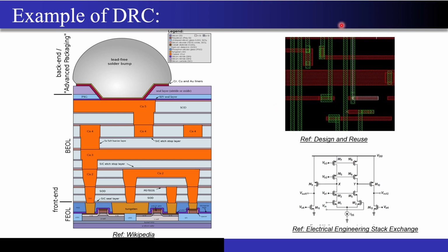So this is what you generally draw as a layout in Cadence, right? Let's say you have a circuit like this. Don't get scared, this is a circuit of an op amp, a telescopic op amp. You will be studying this in the course, correct? I just wanted to show you that there is a connection going from this particular stage to this particular stage over here, so that the drain of one MOSFET is connected to the gate of another MOSFET, correct?